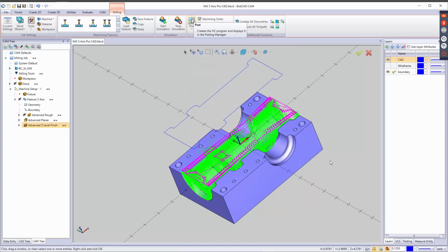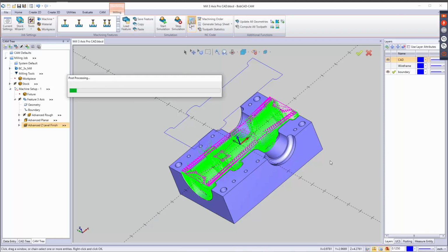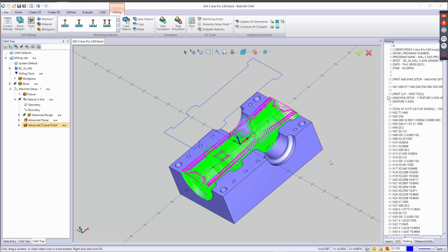And then if I come over here, I usually just tell people to click on the control box or a little controller icon right there. And that generates your G-code, which comes up right here. So I'm going to right click. I could do a save as. If you do a save as, you're going to save that G-code to either a flash drive, network drive, or some sort of destination within your computer.